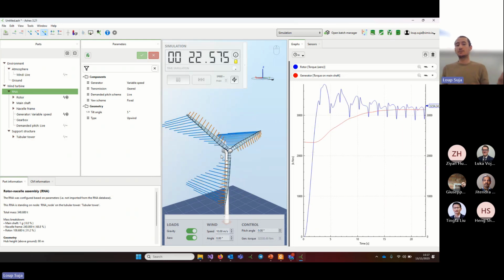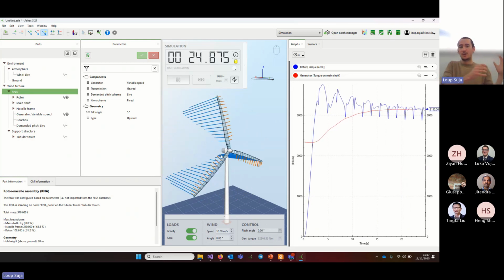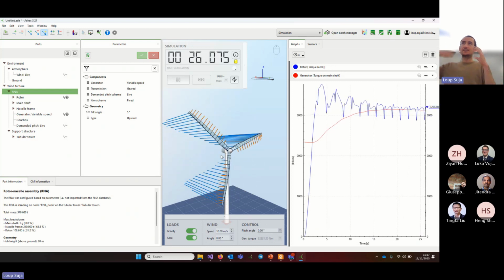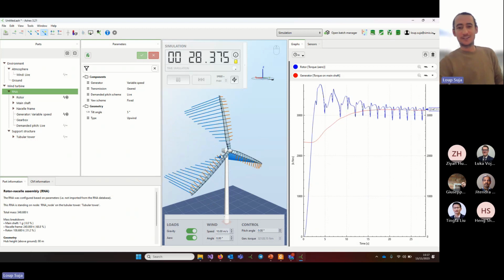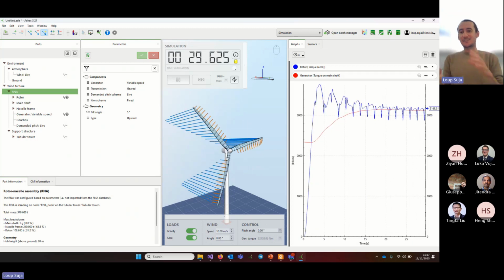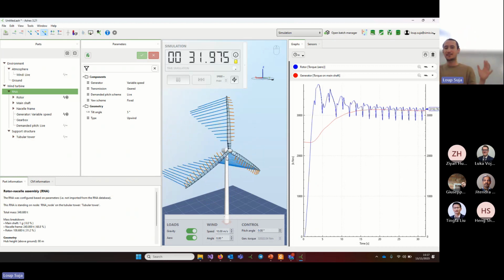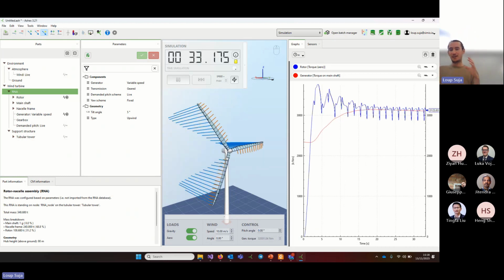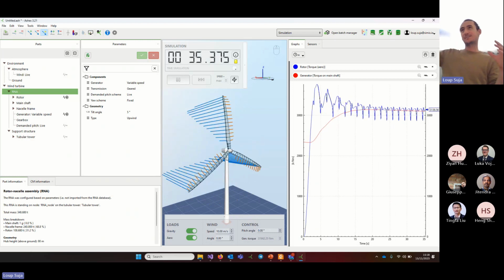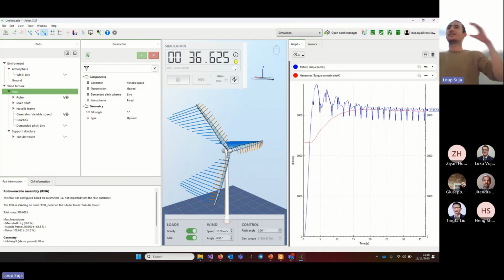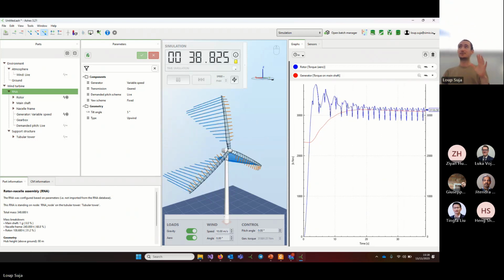You could imagine that you put a big resistive load, and that's producing a torque on this spinning contraption, and that's what's braking the wind turbine. So, once the wind turbine is on a stable state, both are roughly equal. So you have the aerodynamic torque and the generator torque that are more or less equal. Does this make sense? More or less.